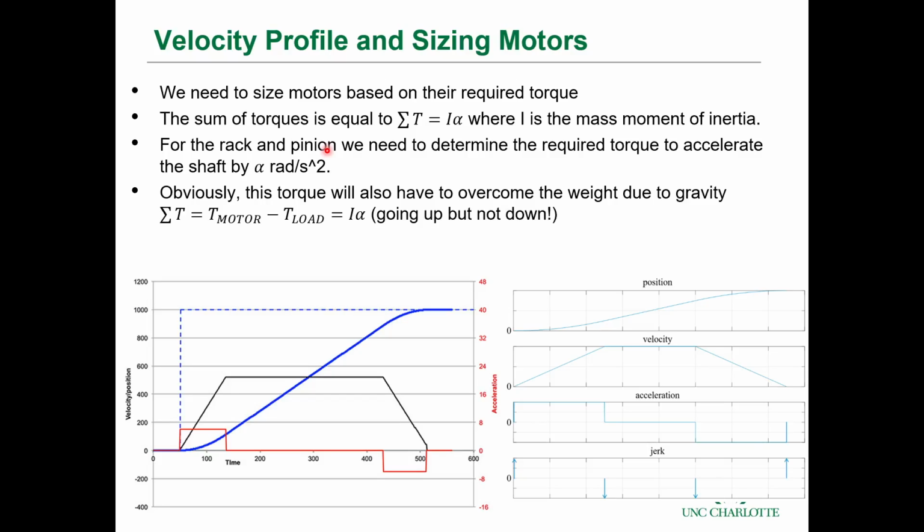The power that you need for the system is the force times the velocity, or the torque times the angular speed. And that angular speed is going to be coming from how long you want it to take your cart to get from the ground to the roof, or those 20-25 feet that it's going to be traversing.